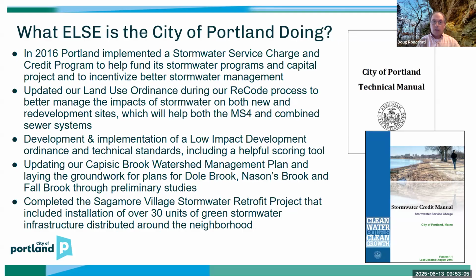And we recognize that there's a disconnect between how we charge for sewer and how we charge for stormwater. When you charge for sewer, you're charging for the amount of water that's metered going into the house, assuming water in equals water out to the treatment plant. That doesn't work for stormwater. When we looked at our stormwater ordinance, we basically figured it's the impervious area that's causing the problem. It's the runoff that's being generated.